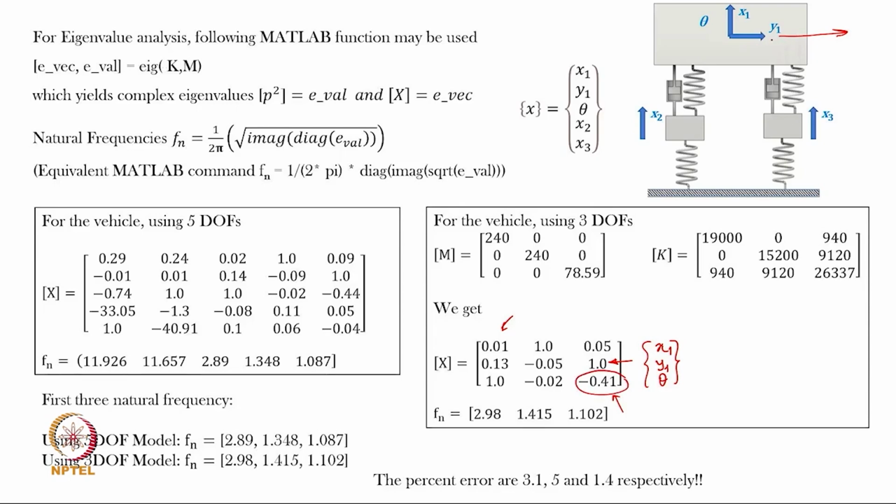So, physically you can see that if the surge takes place along the direction of motion of the vehicle, it is natural to expect a pitch to happen, and that is happening here, because a non-zero value of this theta actually means that in the mode shapes. These are all mode shapes, right. I hope you recall that we discussed the mode shapes of a simple 2 degree of freedom system for one particular case when there were two masses connected like this, right.